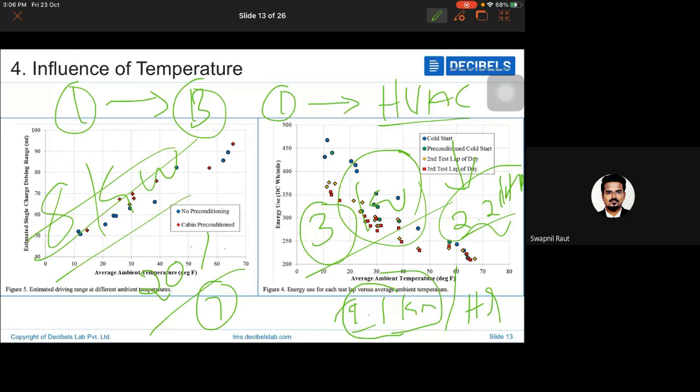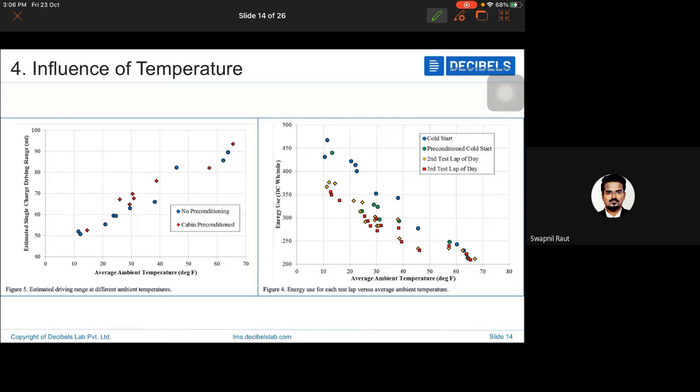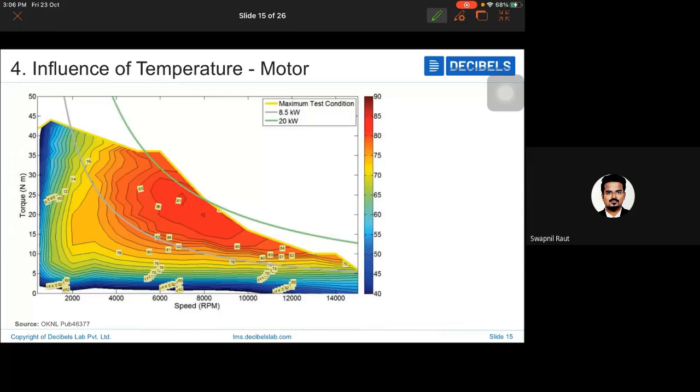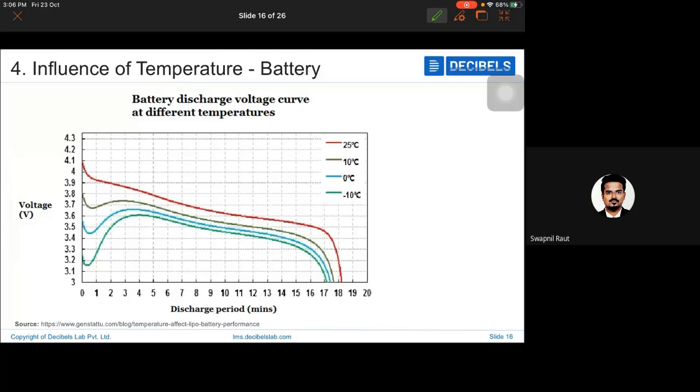Now, what we do as simulation engineers, I could move on to maybe another 15 conditions. Components like HVAC and the battery characteristics are influencing the energy consumption of the vehicle, so we are trying to study all of these parameters. Similarly, the temperature also influences the motor's efficiency. This is a graph I was trying to draw. If you take a battery, the area under this curve is basically the amount of energy it can store. We have done all these calculations in our college days.